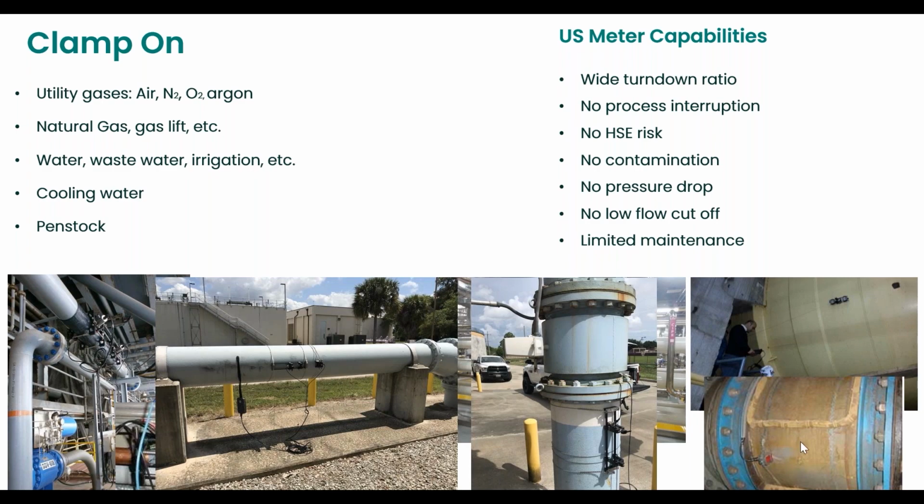You have very good questions. So if you look at the mag meter there, where it is clamped on the mag, that's actually a lined pipe, because it is typically stainless steel there, and you have a PFA or PTFE liner there.